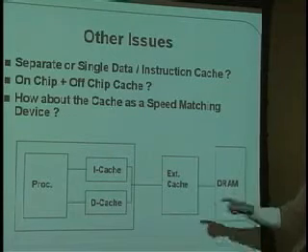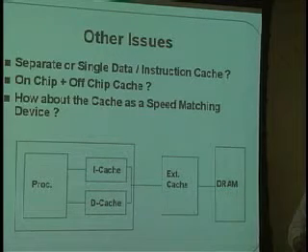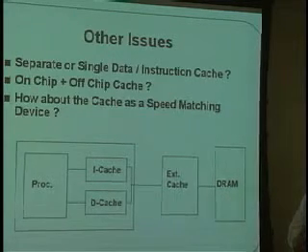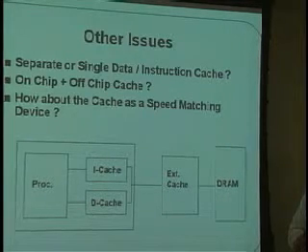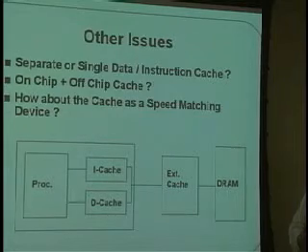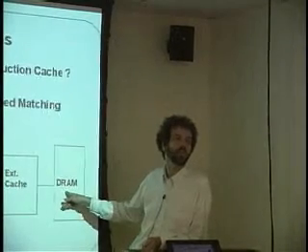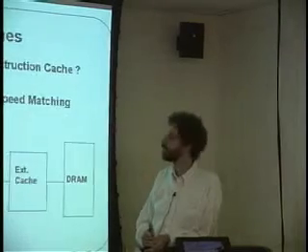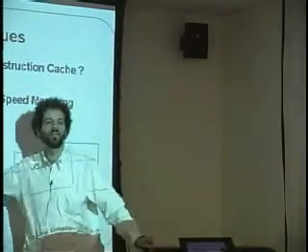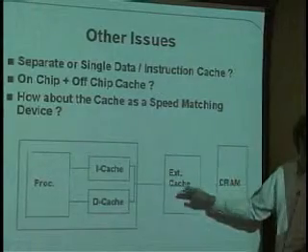That means that whenever it actually gets a cache miss and has to go out to here, even in terms of throughput, don't worry about the 60 billionths of a second, the 60 clock cycles it takes to get the first data item. Once they're streaming in, it takes 10 clock cycles to get each one after that. So this is, even in terms of throughput, very slow. And so caches are fantastic devices for matching disparate speeds between the processor, which is running at 1 billionth of a second, and this thing, which even once it's geared up and streaming a bunch of words out, does 1 every 10 billionths of a second.